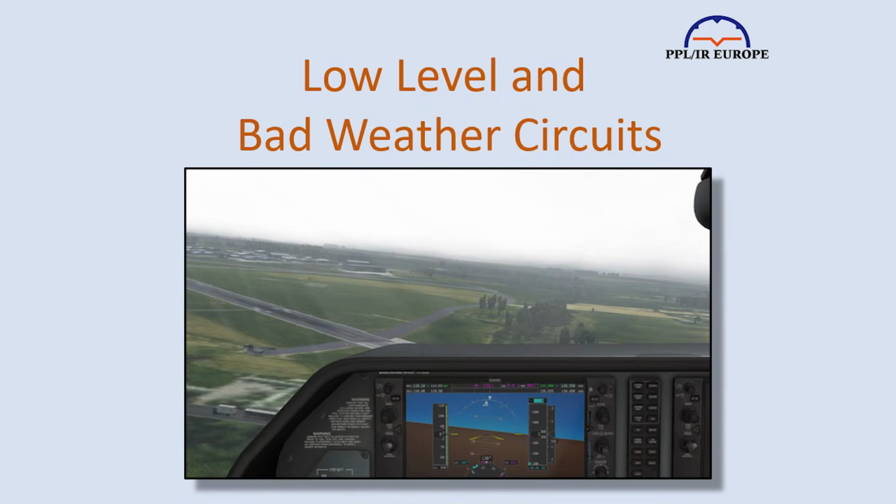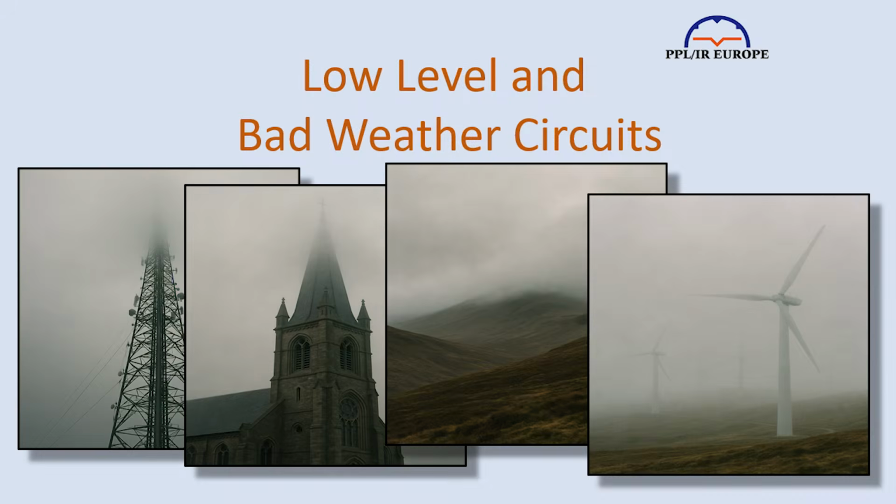A lower-level circuit is flown using the same visual cues as a normal circuit, meaning the circuit will be tighter and closer into the runway. That means everything happens faster, with reduced reaction time. You must also anticipate turns earlier due to lower altitude and reduced visibility. The risk of hitting obstacles is increased. You must be aware of trees, buildings, masts and power lines.